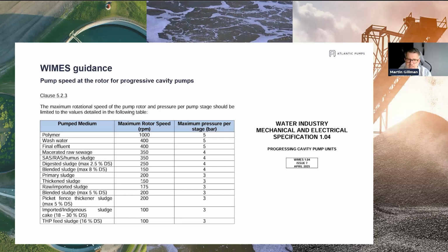So it starts to make sense that in that particular case, remember we talked earlier about that speed, that rubbing velocity, which also incorporates thought about the abrasiveness of the liquid. So let's bring this down to basics. If we're pumping what we deem a medium or highly abrasive liquid or sludge, we want to run our pump as slow as possible to reduce the rubbing velocity. So therefore our wear rate, or our wear effect, is as low or as good as it can be.